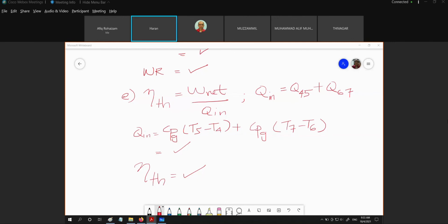Pressure drop is because of viscous flow. Any flow, any fluid, any liquid, any gas which has viscosity will cause pressure drop. It is because of the friction between the internal flow surface and the fluid itself, because of the boundary layer effect.